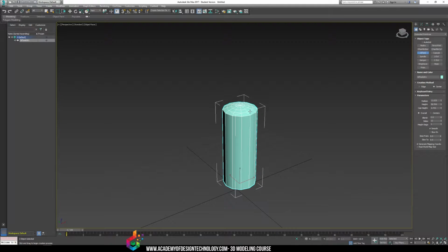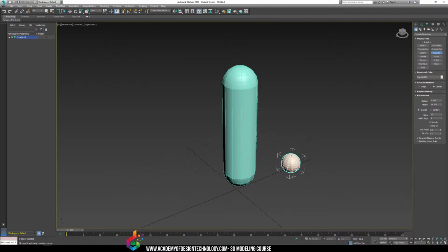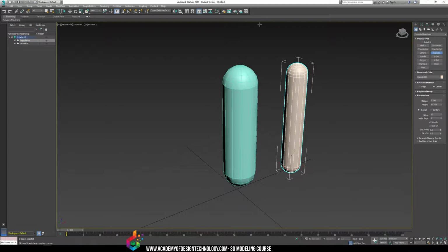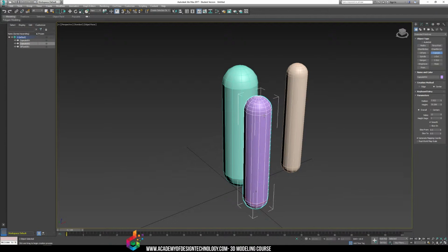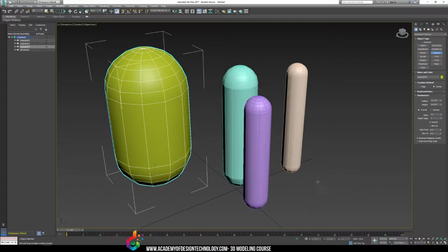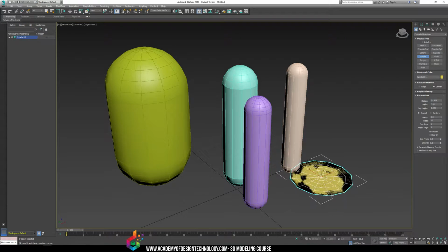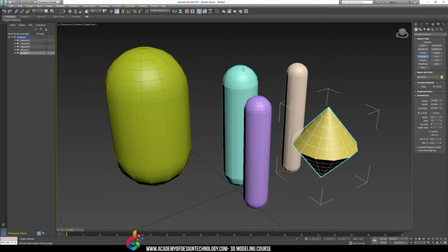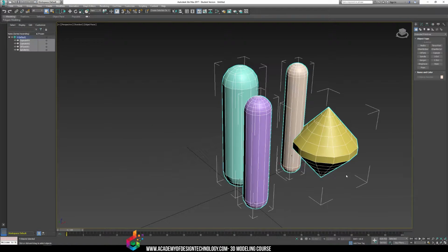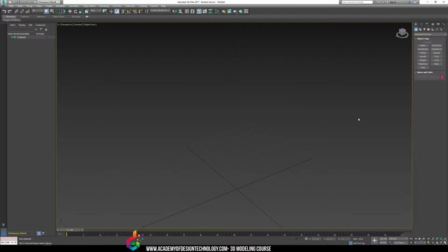I'm going to create an oil tank here as an example. I left click and drag to create the base. I let go of that so I can create the height. I left click again, and now it lets me modify the curve, creating a type of capsule type shape. There actually is a capsule option as well that works just a little bit different than the oil tank, because it kind of gives it this shape automatically. There's also spindle shapes, a little bit more complex, left click drag, and then the third option is to create like a top like shape right there. So don't be afraid to play around with standard primitives and extended primitives to create new shapes to work from.